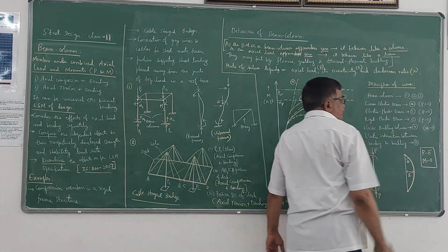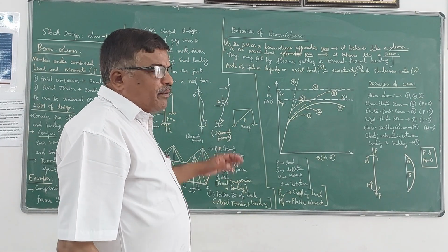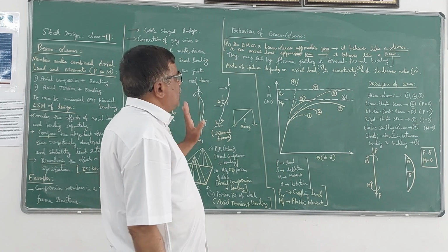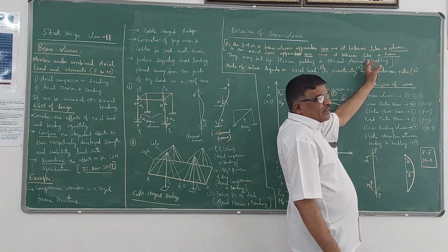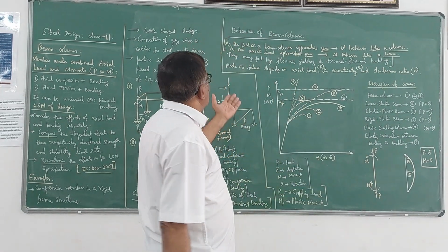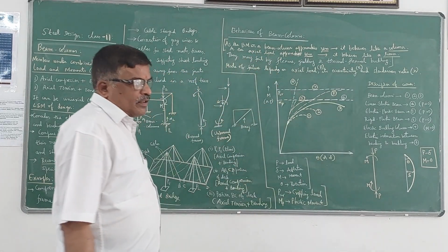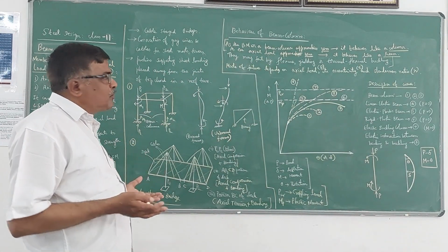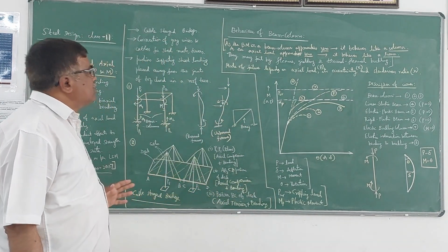So both the compressive effect and flexural effect will be there depending on the values of P and M. If P approaches 0, then only M will be there, that means bending moment, so it acts like a beam. Whereas if the moment value is very small and only compressive force is there, then it behaves like a column or axially loaded member.